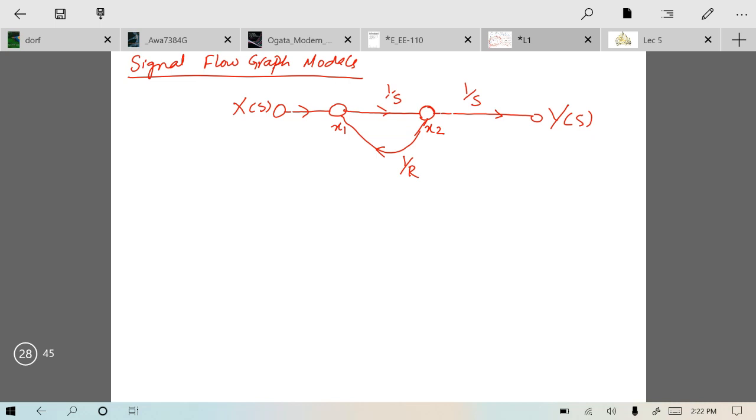There is a formula by which you can directly calculate the transfer function using signal flow graphs. However, in the block diagram reduction technique, no formula exists. In a block diagram, you find a transfer function only by reducing the block diagrams. In a signal flow graph, there is Mason's rule, which enables you to find the transfer function using an established formula.